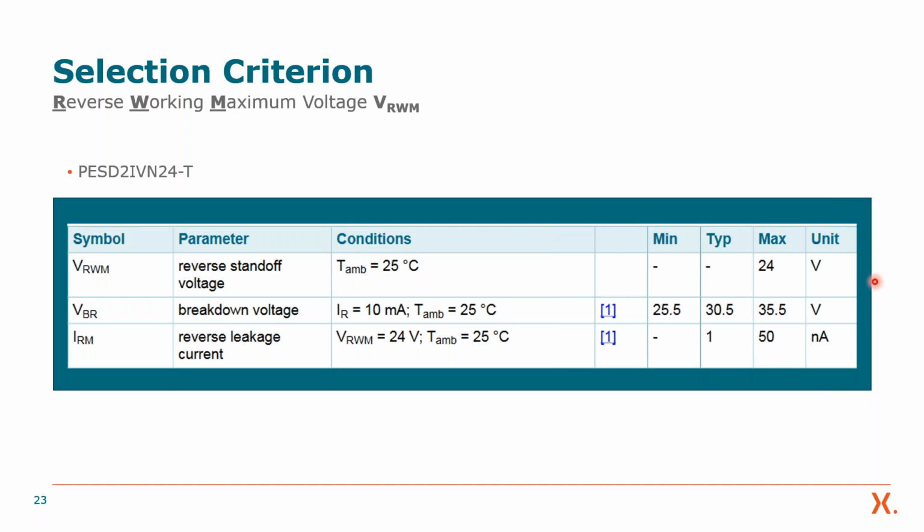Another reason why this is stated in the data sheets is that at this voltage, every test is done. So you could also use this for, I don't know, 12 volt or 5 volt or whatever you encounter as DC on your line. But all the tests are conducted for this 24 volts. So in this case, the leakage current is also evaluated at this voltage. Yeah? So it's just a reference, but it does not guarantee you anything.